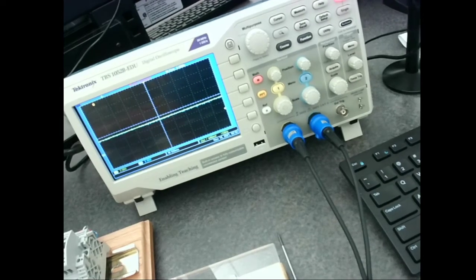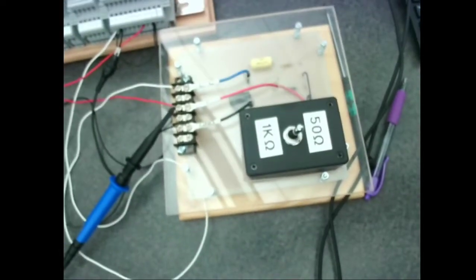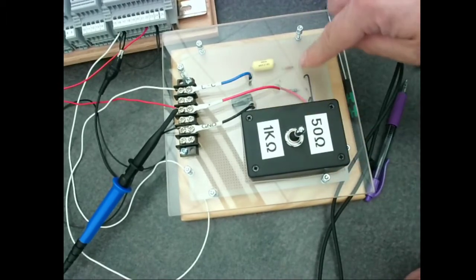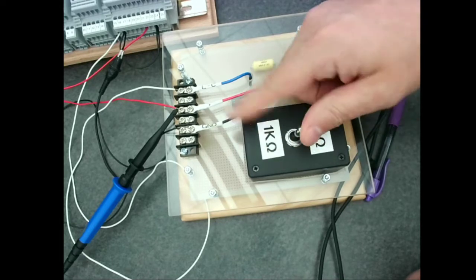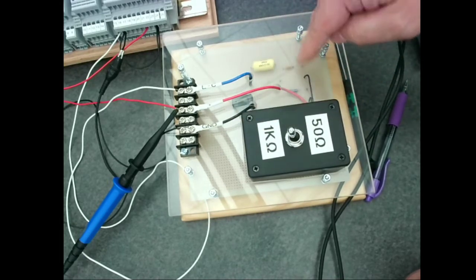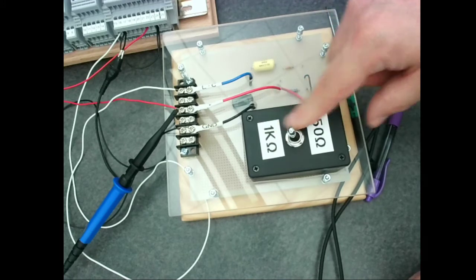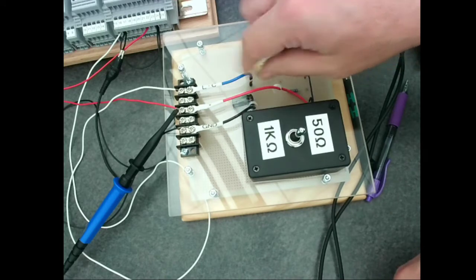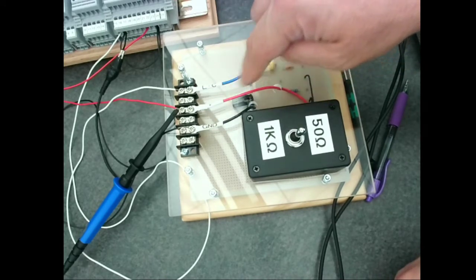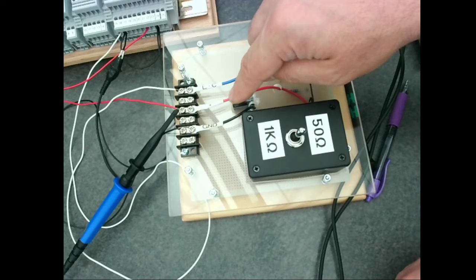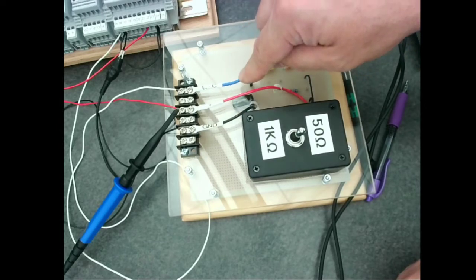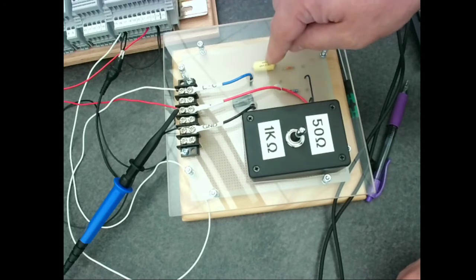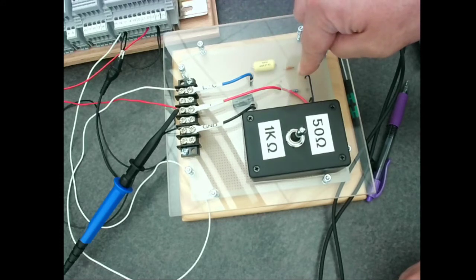Okay. So our system is an RLC system. We have this little system made up here where it actually has 2 different size resistors. We can flip a switch to switch either to a 1K resistor, which is obviously a lot of resistance compared to a 50 ohm resistance. And what we're going to be looking at, our output is going to be the output across the capacitor. So it's a series inductor, capacitor, and resistive circuit.